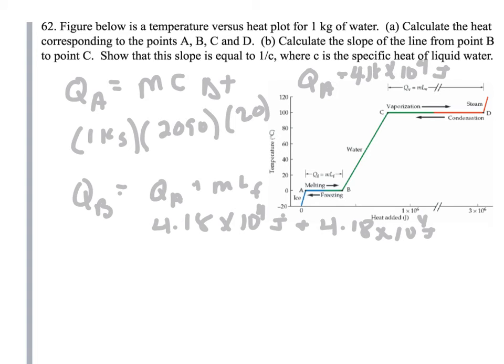I'm sorry, I would back up. I made a mistake there. So that's not our latent heat. That's the specific heat we just calculated. So we have our heat that we just calculated, and then our mass of 1.1, and then our 1 is just 1 kilogram, times the latent heat of fusion for water, which is 33.5 times 10 to the 4th. And again, this Q up here, write that a little neater.